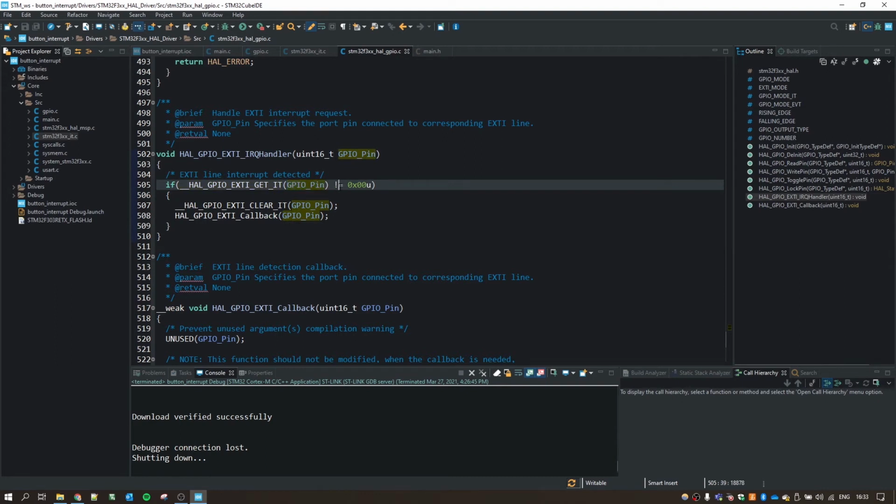And that is not equals 0, which means if I got an interrupt, that means that I have a 1 over here, and 1 not equals 0 is true. So then I successfully go inside the if statement, and then I make sure to specifically clear that interrupt assertion. By doing that, every time unnecessarily I don't make this particular if statement go true, and then we keep on going inside this if statement again and again.